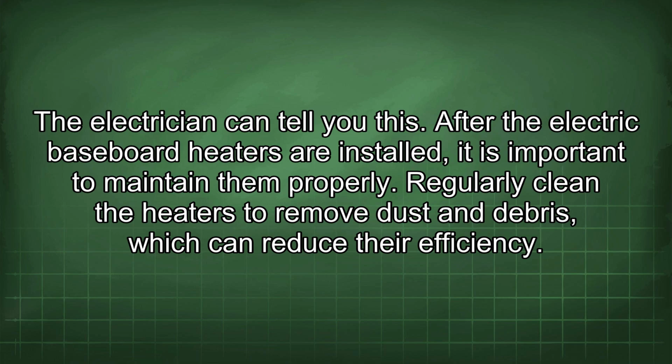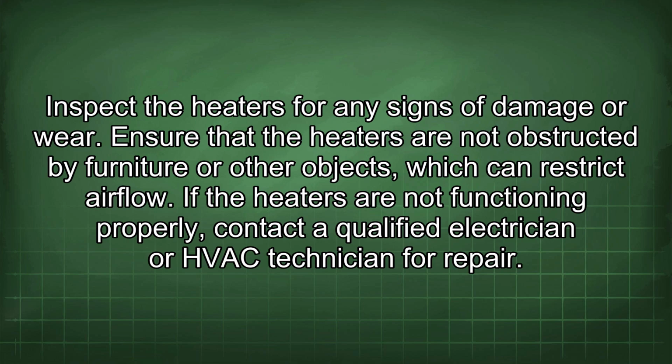After the electric baseboard heaters are installed, it is important to maintain them properly. Regularly clean the heaters to remove dust and debris, which can reduce their efficiency. Inspect the heaters for any signs of damage or wear. Ensure that the heaters are not obstructed by furniture or other objects, which can restrict airflow. If the heaters are not functioning properly, contact a qualified electrician or HVAC technician for repair.